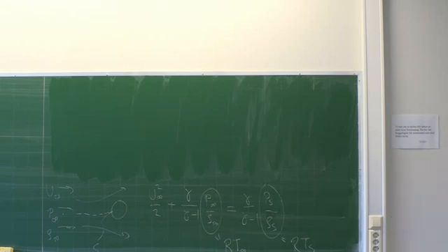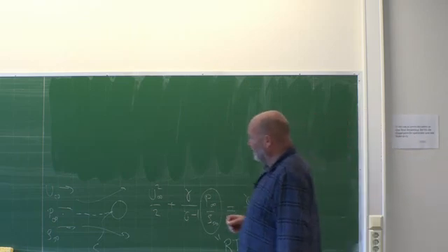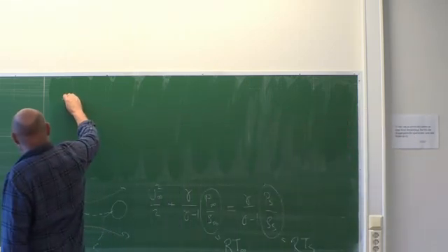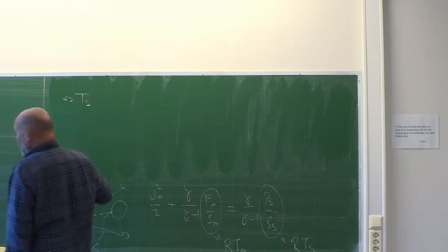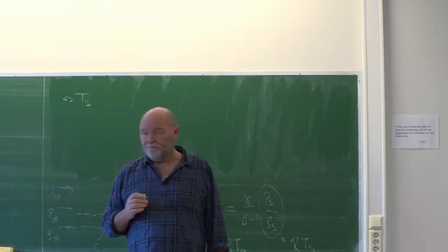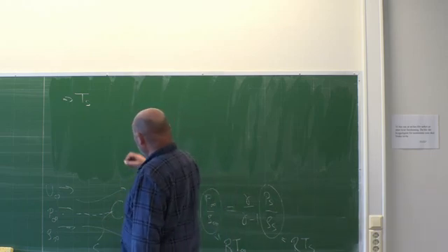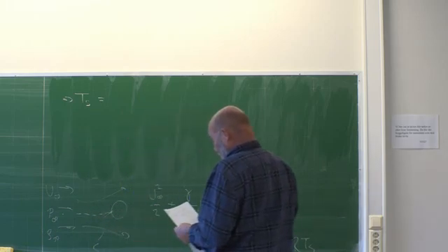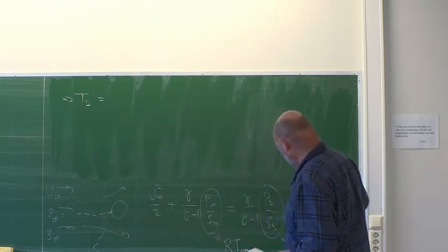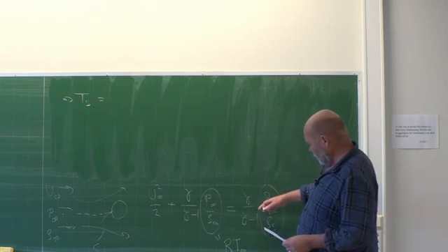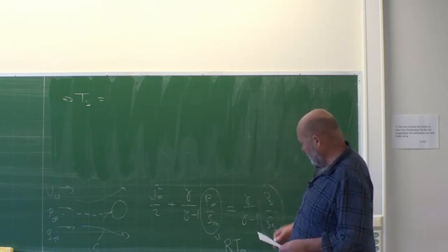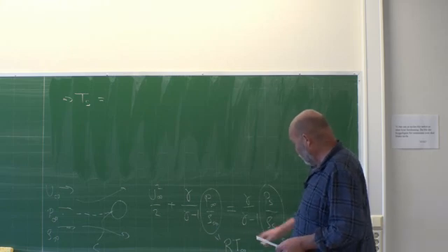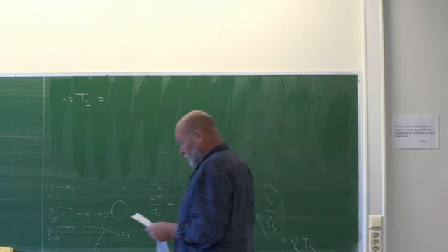So you can rewrite this equation quite easily just looking at the temperature. So now we are talking about how hot it will be in the stagnation point. And that one will now equal, and then you will have something. Let's see now. We have to multiply with gamma minus 1 over gamma, and then move this R on the other side.